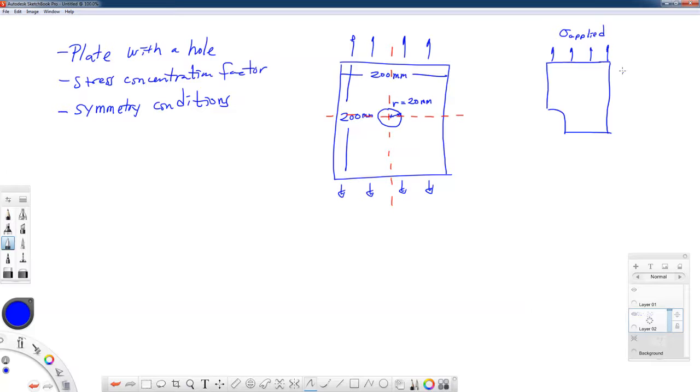And that would make the coordinates, let's just go ahead and put these in. 20, 0, 100, 0, 100, 100. And 0, 100, and 0, 20. So these are key coordinates. We're going to want to map this out when we get ready to construct our geometry for this finite element analysis. Now these are all, like I said, in units of millimeters.